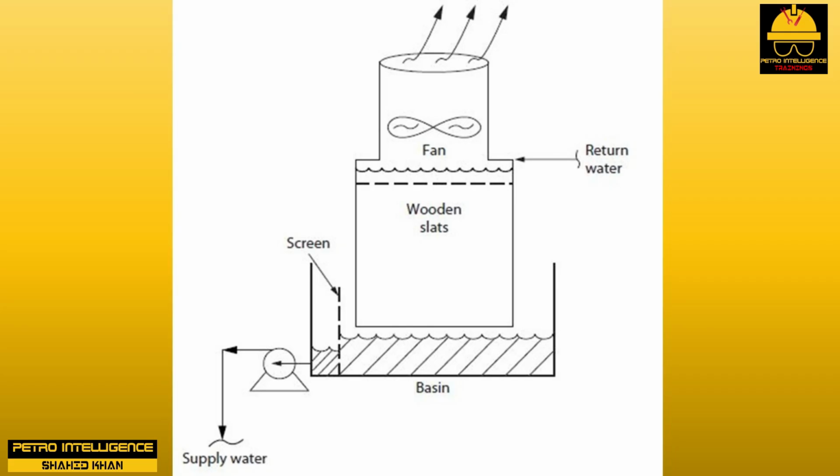He throttled back on the cooling water flow to dozens of exchangers. Several of these water coolers had not been used for years, but no one had bothered to block in the water flow. He spent most of an afternoon on this activity. Based on the combined water temperature returning to the cooling tower shown in picture, he had reduced the total circulating water flow by 20%. But the water flow to the hydrotreater effluent cooler had not increased at all.